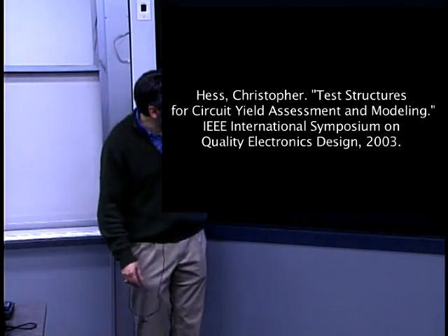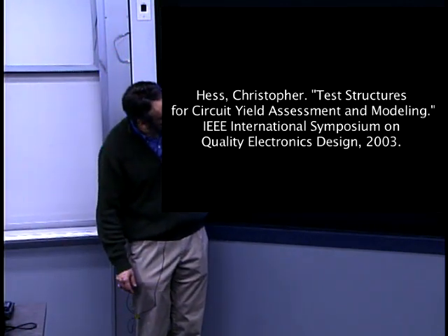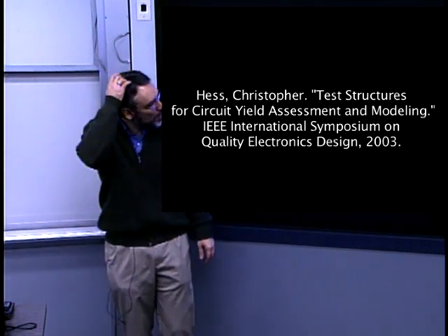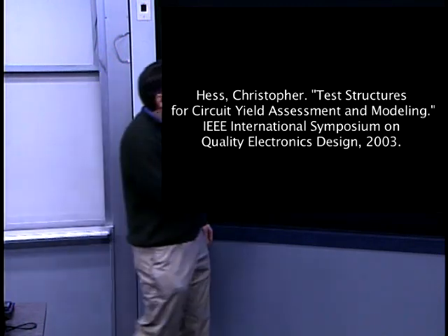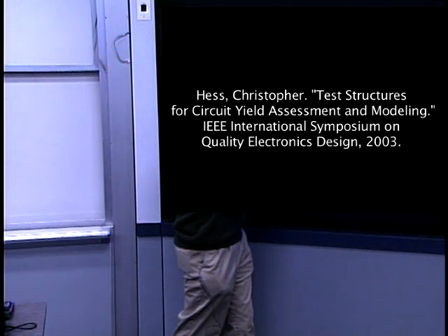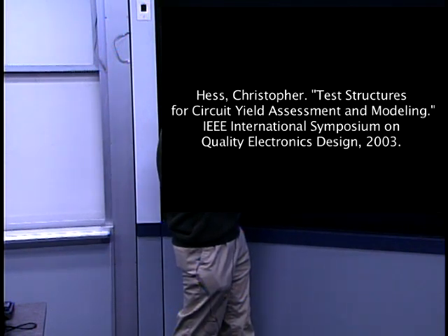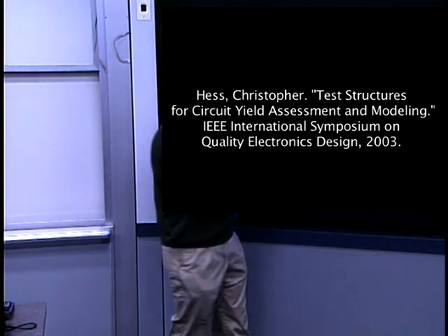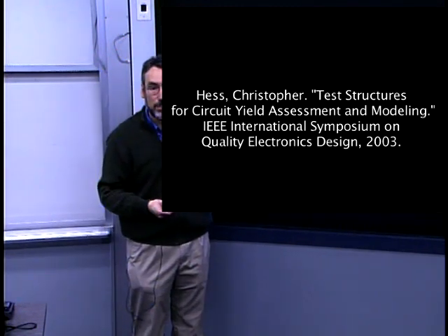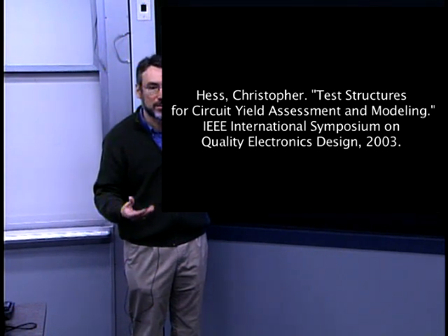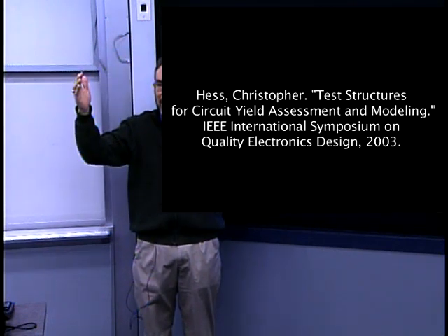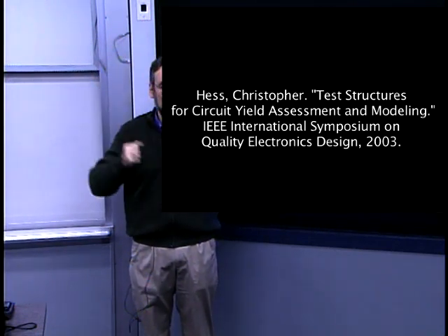And what I've pictured here is a metal layout, a metal pattern structure referred to as a nest structure that allows one to build a large number of these sort of snaking lines and electrically connect between these different lines in order to test if there is a bridging defect between lines and count the number of those events. So you build this structure to sort of spatially sample as large an area as you can to try to capture some number of these defects.